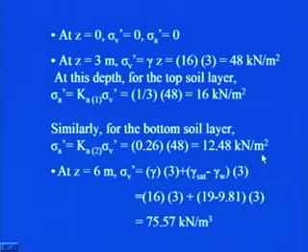Okay. So you see, whenever there is any interface, whenever there is a change in the soil, maybe due to the presence of either a water table or maybe there is a layered soil system, there you have to split it into two parts, that is one just above the interface and another just below the interface.